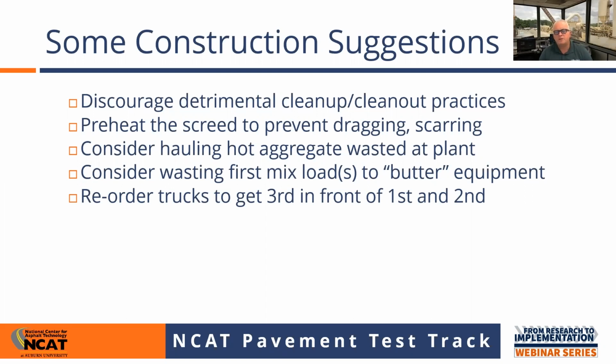One of the other things that you can do that's really easy is reorder trucks, and maybe take truck number 3 and put it in front of truck number 1 and truck number 2, because the mix temperature is going to be much more stable at the plant in that third load than it typically is in that first and that second load. Now, in that scenario, you're not wasting any mix.